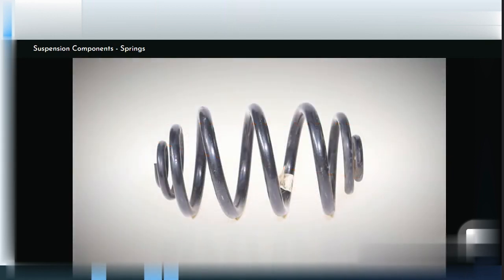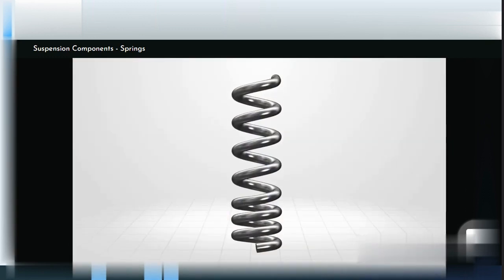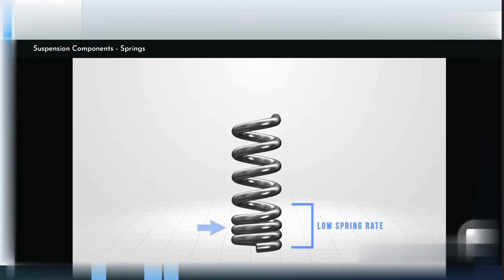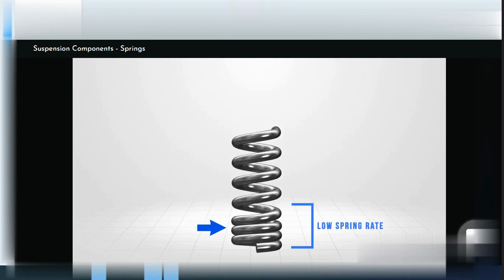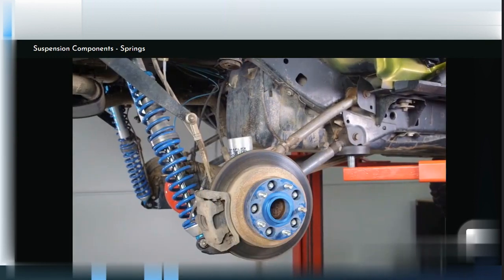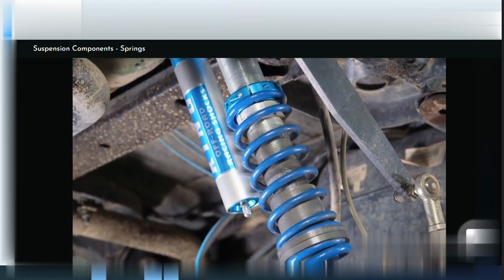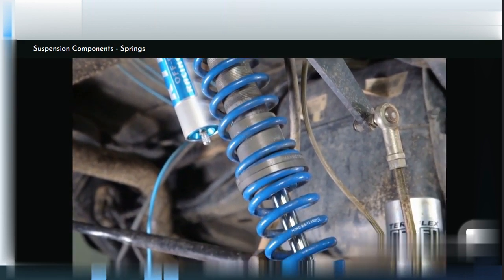Variable rate springs are easy to spot because they are not symmetrical. Typically, one end of the spring has tighter or more closely spaced coils. As the spring is compressed, the soft coil on the tightly wound side will collapse, coming into contact with each other. When this happens, the rest of the spring starts to compress at the second higher rate. Sometimes, to achieve the desired rate, 2 separate springs are used at the same time with a special perch mounted between them.